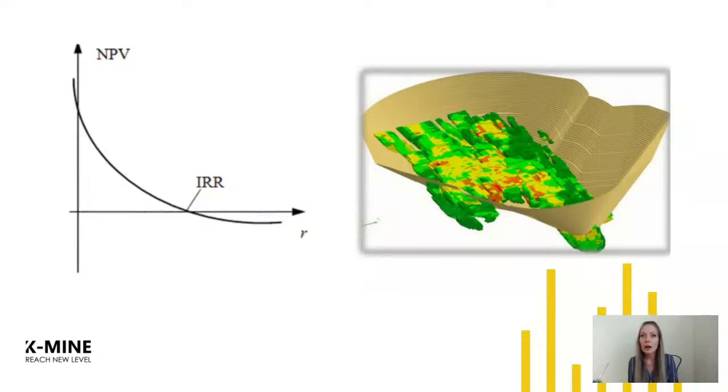All calculations can be performed under various mining scenarios or with various cut-off grade options to select the optimal model options. And in Chemine, you can get a more comprehensive approach to mineral resource estimation if you use a multivariate analysis of the components and a systematic approach in research. For example, a block model can simultaneously contain information on technological types according to the processing method, technological grades in terms of enrichment indicators, and industrial grades of ore that are outlined according to specified conditions.